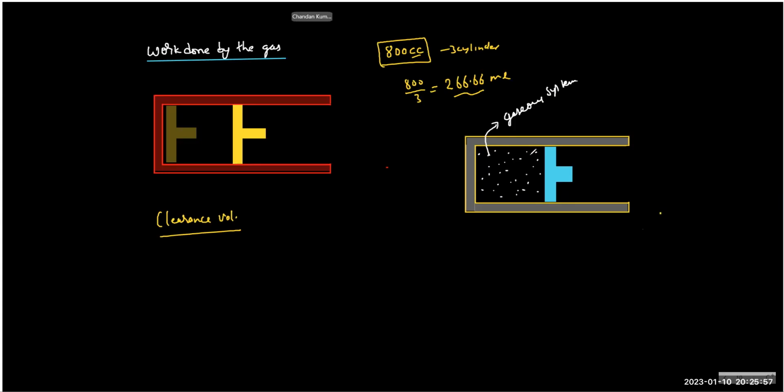Yeah, of course, some of the heat produced can be absorbed by the piston. But generally, we believe that if the walls are adiabatic, they will not take any heat, or if they are metallic, they will take a very small amount of heat to raise their temperature. Okay, so the gas is your system. The movable piston will be the immediate surrounding. So any work performed will actually go to the piston, and the piston is also in connection with its own surrounding. If I think of the piston as a system, then who are all its surrounding?